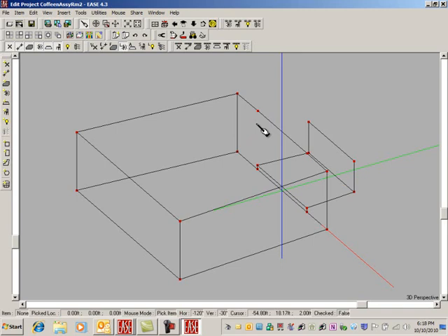Now we have the ceiling here to add, and there's several ways to do this, but I think I'm going to show you the simplest. The first thing is we have a little flat panel in here, and it's back 1.5 feet in the y direction. What if I duplicated this guy, but I don't want him to go straight back. I want him to go back at this 4-degree angle.